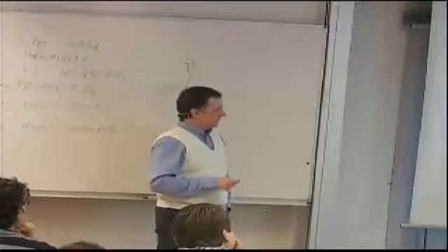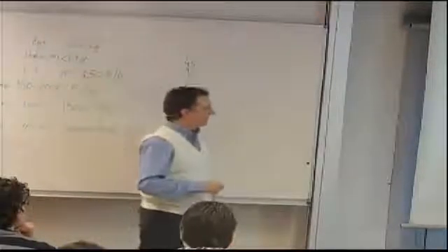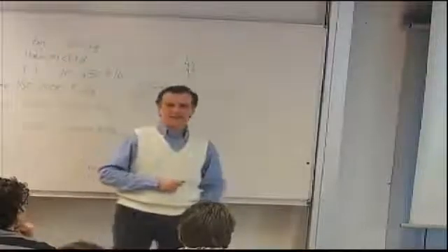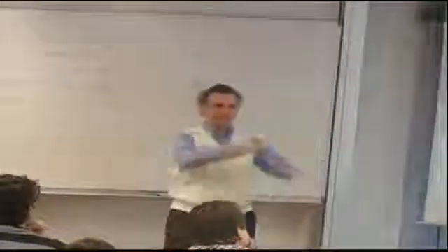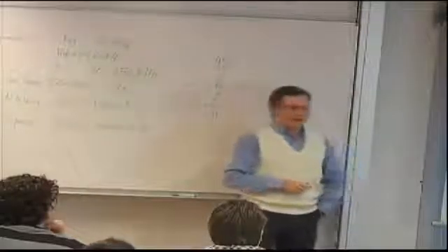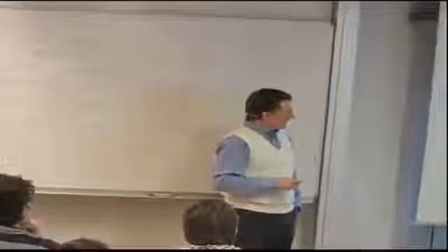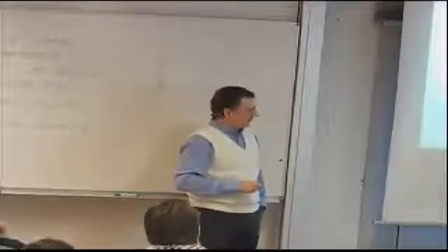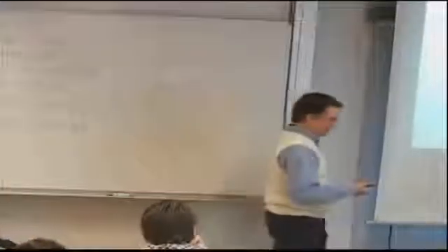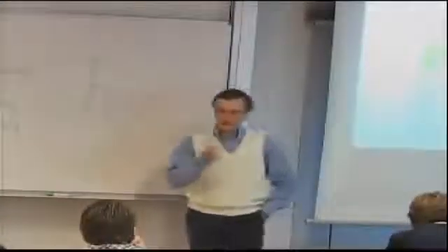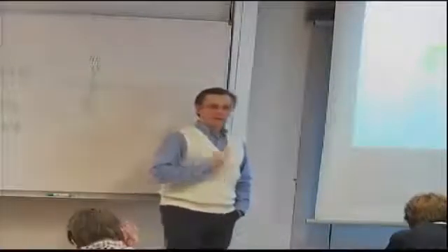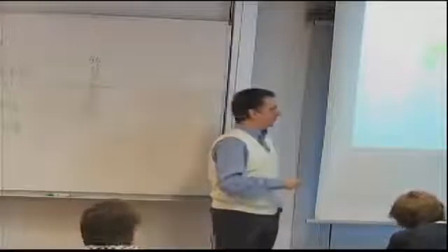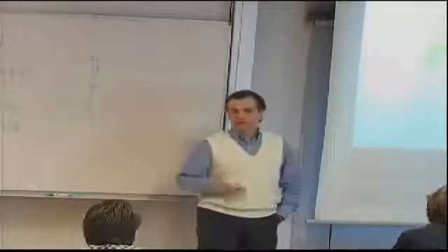And if we use a quasi-isotropic material, then you will find that it's actually slightly heavier, 3% heavier than aluminum, and this is the typical black aluminum. Black aluminum design uses quasi-isotropic, which means the stiffness is the same in all directions, and it's not very efficient. If you use the more efficient design we just defined, then you are down to about 30% savings. So all of a sudden, the need to come up with the correct stacking sequence that will really take advantage of the composite capabilities becomes very important, because if you don't do it right, you will end up with either the same weight or, God forbid, even higher weight.